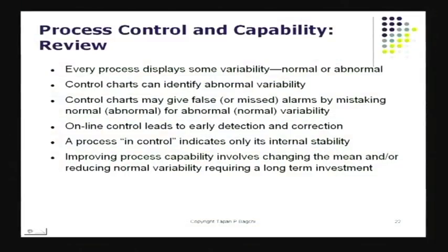If you're worried about whether there is some way I could get an idea of how good my process is, how poor my process is, look at your control chart. If there are a lot of statistical points, these are the X bar values or the R values, beyond the control limits, clearly it's not very likely that your process is capable. This is something you've got to worry about. So if you're starting out trying to control a process, of course you could produce a histogram of the output. But it would be a better idea to try to run a control chart and take a look at whether there are many assignable causes that are also impacting the process.